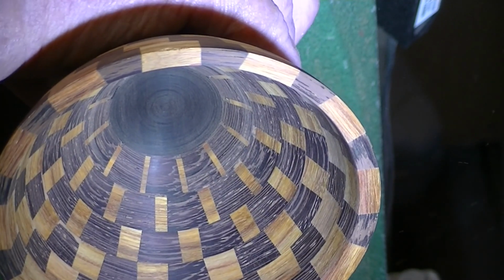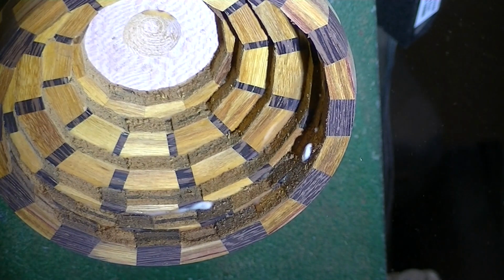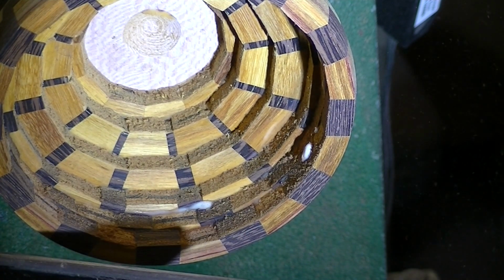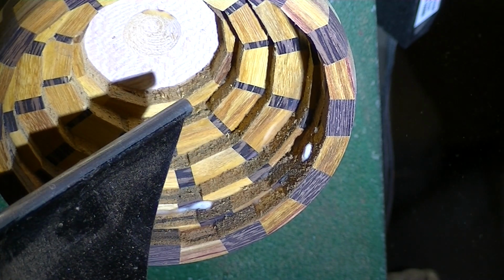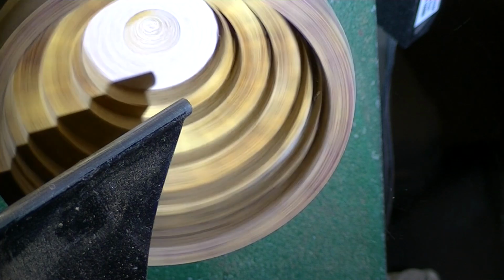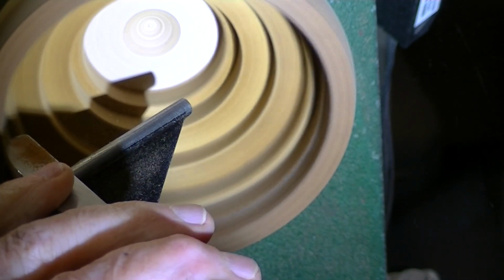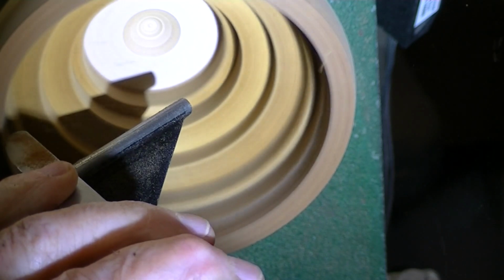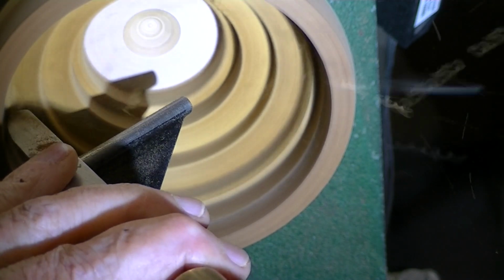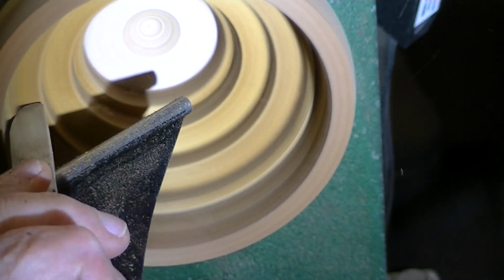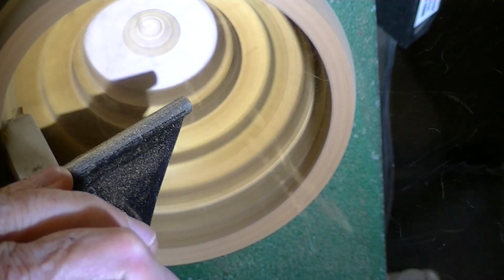So we're going to take it off. We're going to place that with the other portion, that which will be the top of the vessel, which as you can see is mostly canary wood with just a little bit of Wenge spacers in there. So we have to do the same kind of cutting again. And here we go with a typical round nose scraper, knocking the corners off as we go down inside. I'm working a lot on the first 2 or 3 rows just simply to get them perfect, as close as I can, before going down and tackling it deeper.